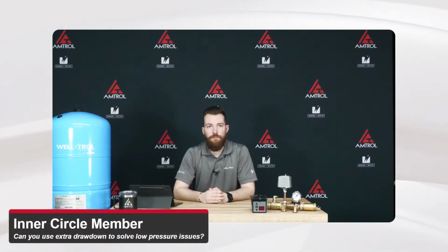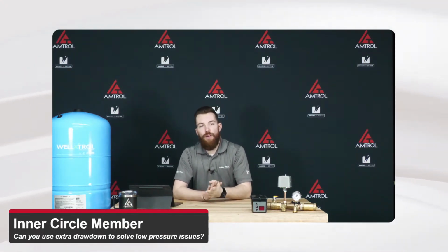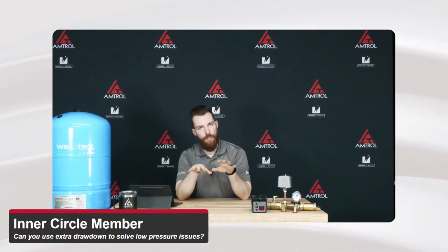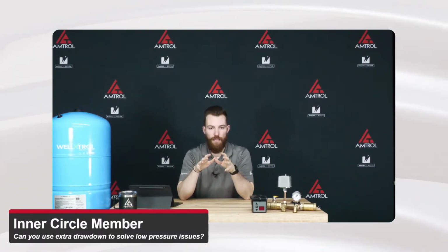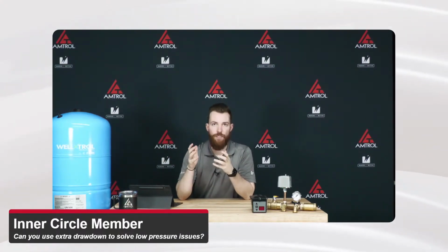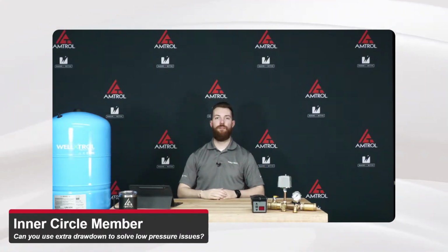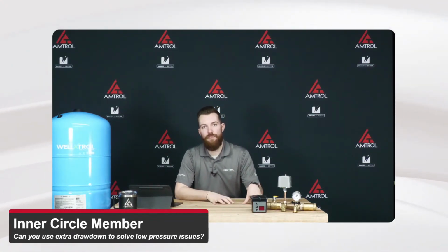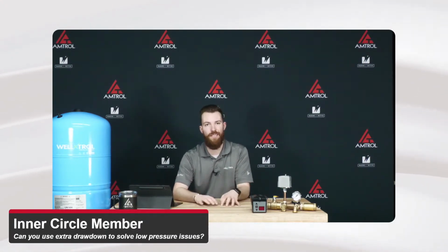All right, our next question. Can you use extra drawdown to solve low pressure issues? I'm going to dig into that question a little bit. Flow and pressure are different, and if you watch the RP presentation Gabriel did, we went through that a little bit. When we're sizing for supplemental drawdown, or using the extra drawdown in the tank, or just any pressure tank in general, it's supplying volume, not pressure. I know it's called a pressure tank, but in reality, it's giving you volume. So when we size these tanks for these systems, the idea is that we're trying to fill a gap in the volume, not as much a pressure requirement.